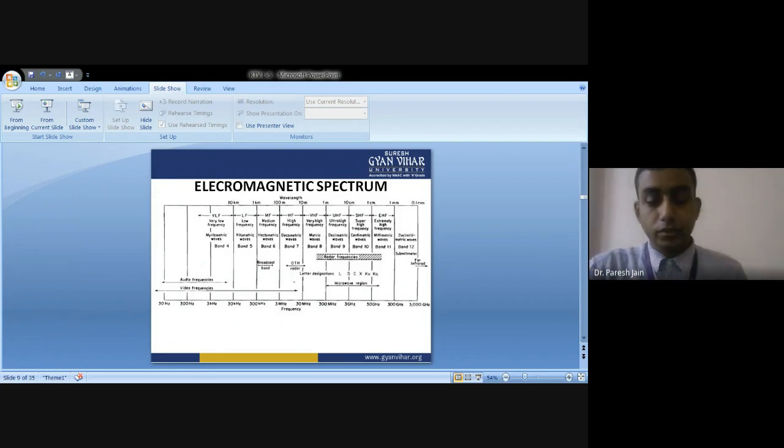It is a question on antenna properties. Next question: what radar circuit determines the pulse repetition rate? Discriminators, time synchronizer circuit, artificial transmission line, pulse rate indicator circuit. Answer is B. Given a pulse width of 8 microseconds and a duty cycle of 8%, determine the pulse repetition time of the radar system. Answer is 100 microseconds.